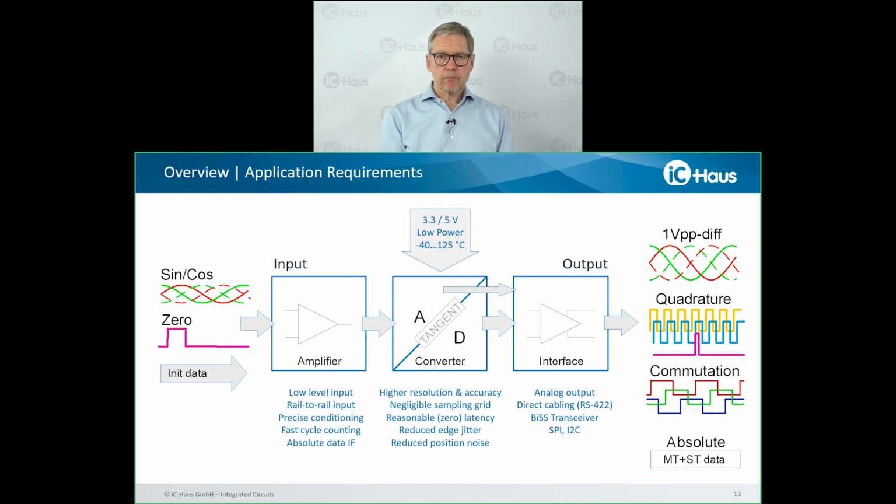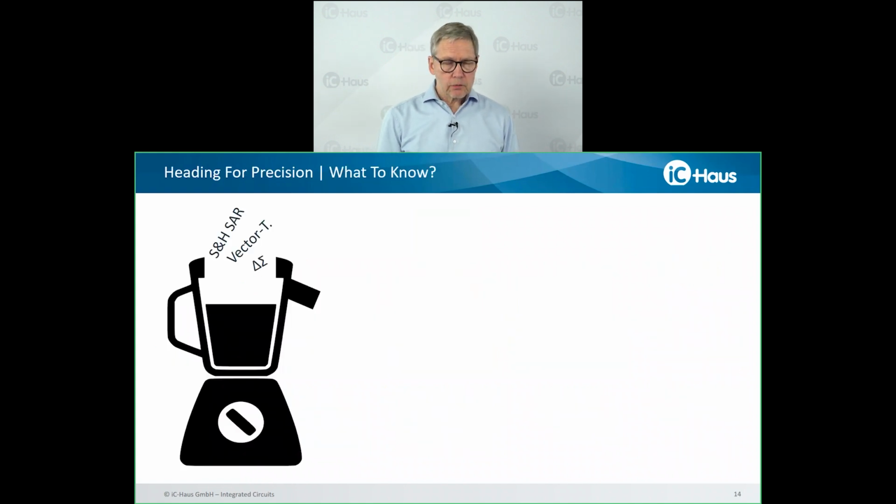For the outputs, that's the section where you don't like to waste any board space. So to solve the space constraints of small read heads, we have therefore integrated all the line drivers required to go directly on the cable. Your choice of a converter device may also depend on the type of error correction you need. You can imagine each IC needs to be cost effective, so any design comes with trade-offs. And it's hard to say that one device fits all.